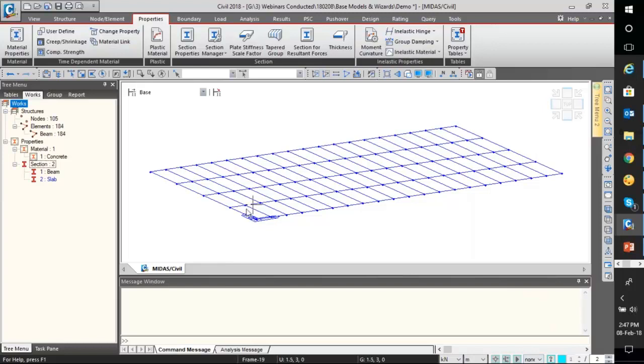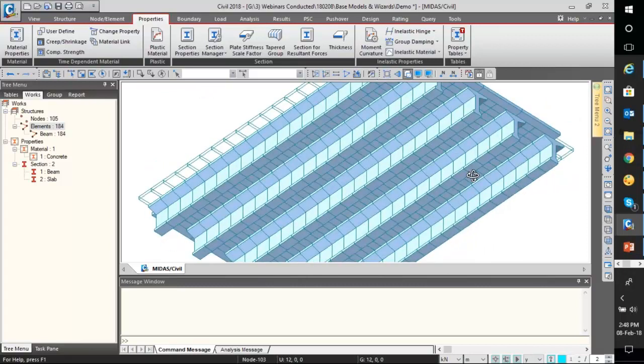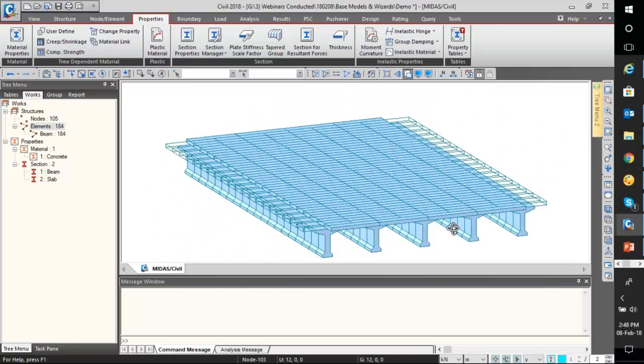So if I want to select only the beams which are perpendicular to the global y-axis, so here I could select Y. This is basically my selection filter. Then I could click on select all. For transverse, I'll apply the slab property. Okay, it's just like that. You select it and you drag and drop from the tree menu, and that property would be assigned to it. So if I check 3D view now, so this is how it looks. Okay, my I girders and my slab.